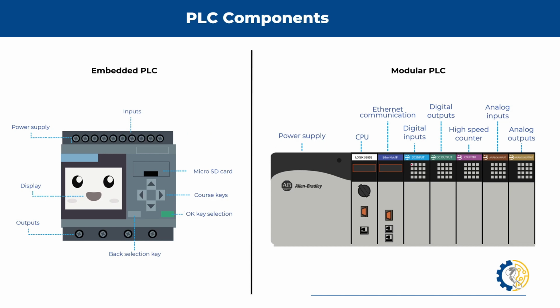If you notice here, we can start visualizing squares. These squares are LEDs. The newer PLCs already have them on their cards in general. Most of them, actually. So we have our input card, it has its LEDs, and if that LED is lit up, let's say at point number one, it's because I have connected my sensor here and it's starting to detect something. That helps us visually to know if the sensor is working or not.